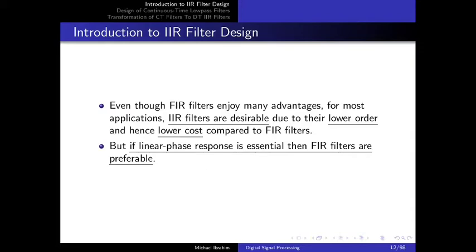And also there is this category of filters that's called adaptive filters, filters which change their response based on the channel or based on certain parameters. These kinds of filters are usually preferred to be FIR because changing the filter response will not affect the stability of the system since FIR filters are always stable. But if you have an IIR filter which is adaptive, changing the parameters of the filter might result in an unstable filter.